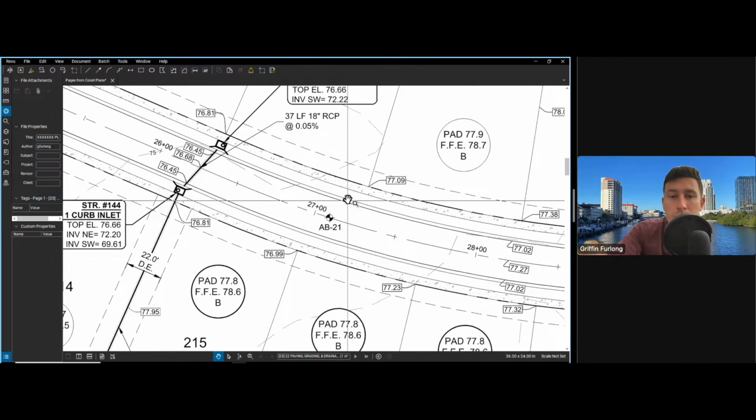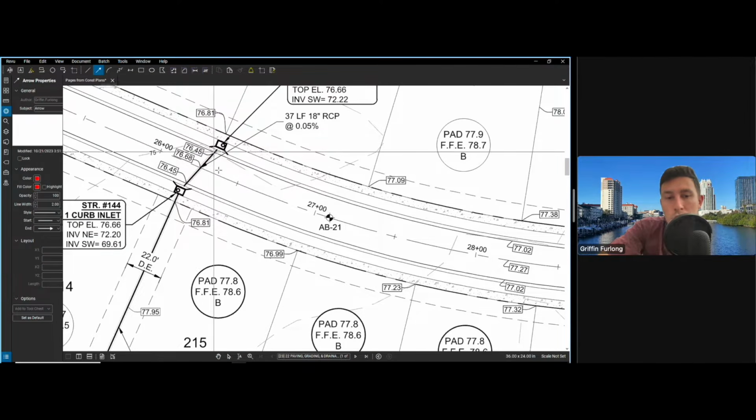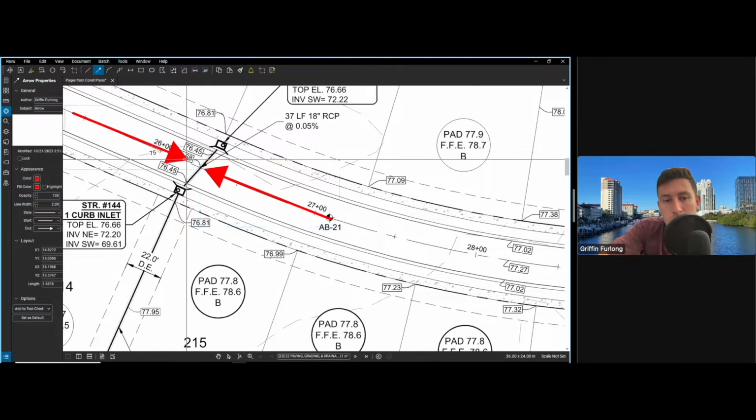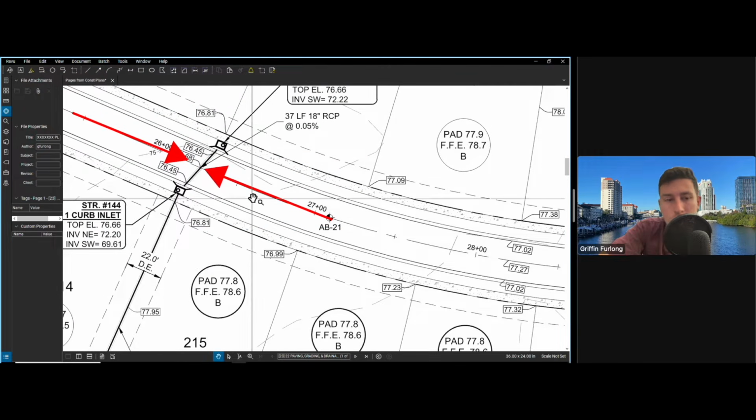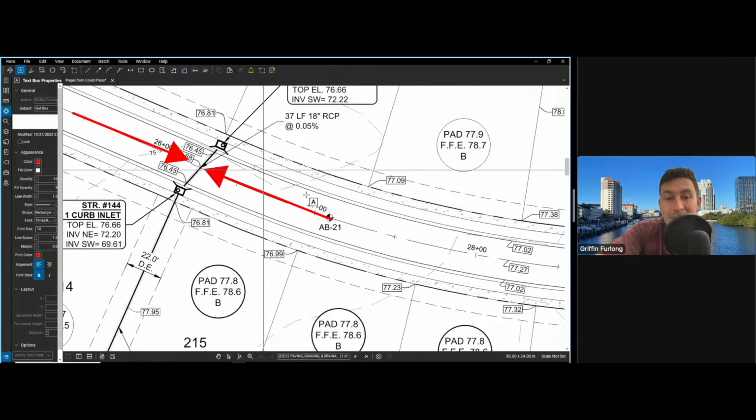Okay, now that we've done a refresher on slopes, I want to show you what are some typical slopes that you might see in a residential neighborhood. So a typical road profile grade, which means, if I'm traveling across the road here, or traveling down this way, since technically that's how we're grading right now. Typical road profile grade going along this road will be anywhere between 0.32%, but the average for road profile grade lines will be 0.32 to around 2%.